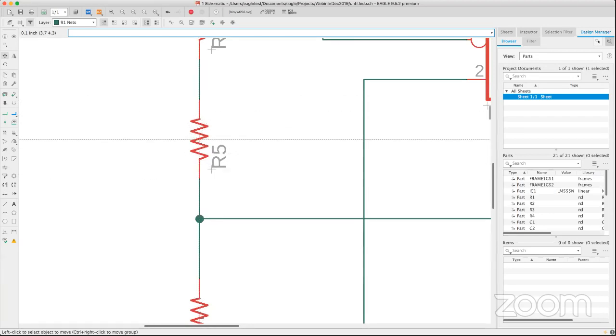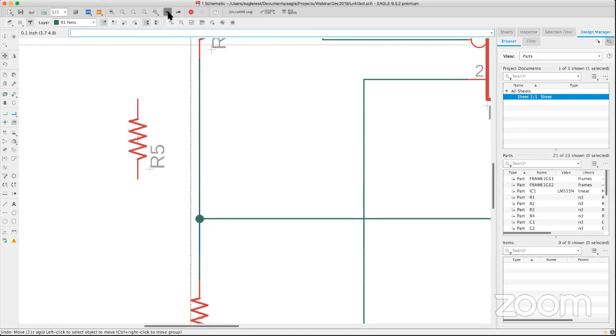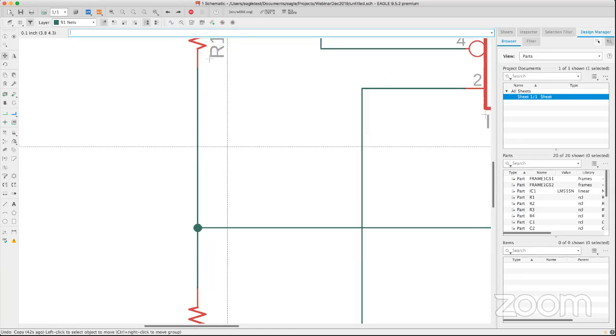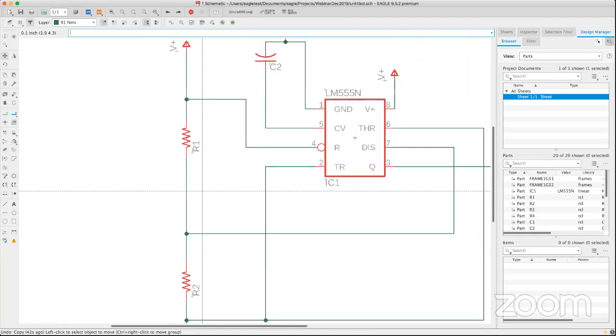Okay? It automatically gets that. It's extremely useful, because sometimes you forget to add a component, and instead of having to delete the nets, you could actually just drag the component in between the nets that are already there, and it will actually be adopted by it. Just wanted to show that because that has come up in the past as well. So it's a good tip to know.